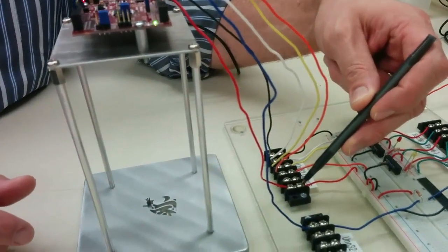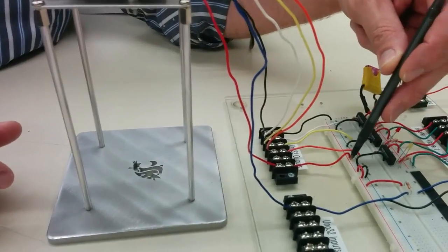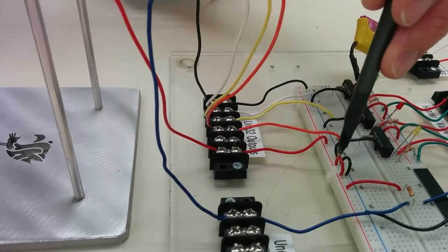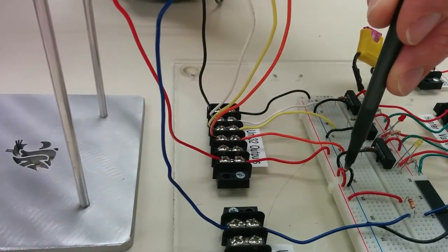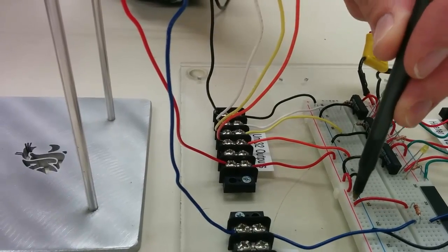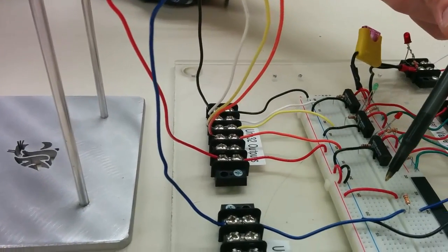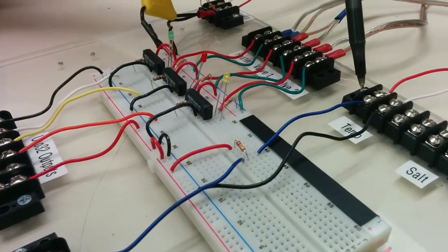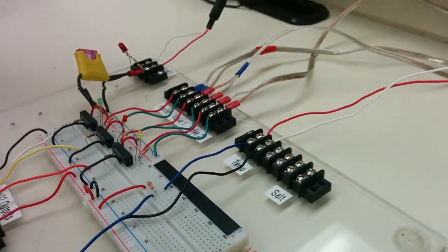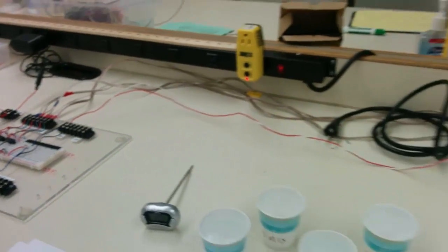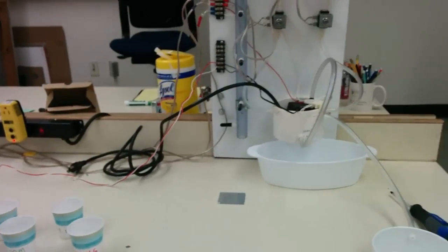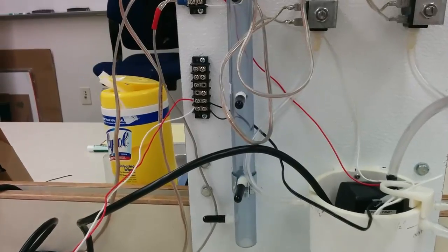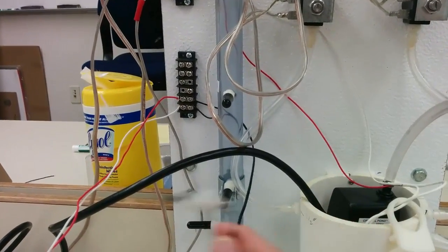It comes down to the terminal block and gets jumpered over into the rail of the breadboard. Now this breadboard, the two sides are divided, so we put jumpers in here for positive and negative, and so here the 3.3 volts comes across through the resistor, that 10K resistor that was on that circuit, and then out to the thermistor. So if we follow these wires all the way over, red and white wires will be going out to our thermistor. On the terminal block, they're tied in here, and then the thermistor is actually this device right here.